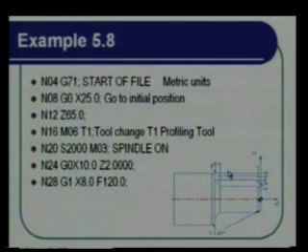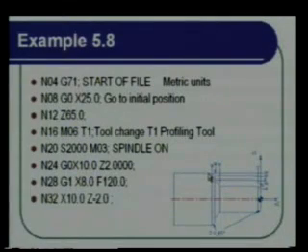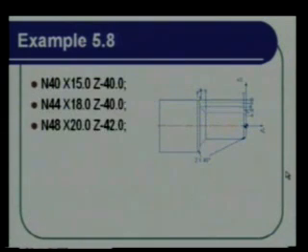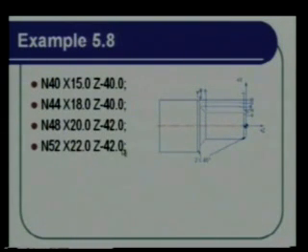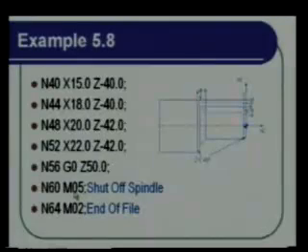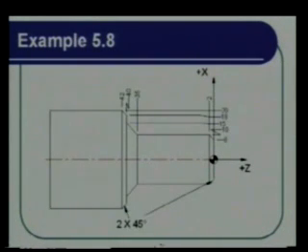Position, go to the depth, so I go to the 8, go up to this point and then retract, go to the start point. So it's simply going through those steps, and every time I go through, give one more step, and then stop the spindle and end of the program. So all I am going to do is simply locate the coordinates. I will have to locate the coordinates correctly. That is the most important part in cut planning.